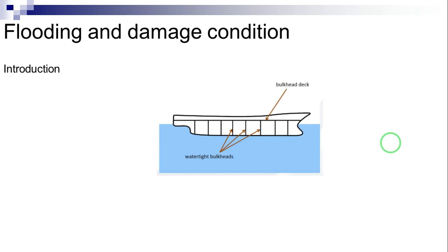Then, even with relatively large draft increases, the deck does not submerge, the waterplane area is not reduced, and the metacentric height may not be affected and may be sufficient. If the deck does not submerge, no openings are submerged.